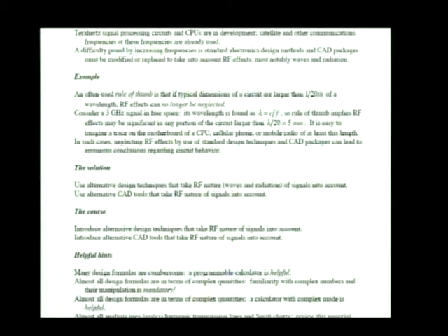That's a pretty tiny distance. Still, 5 millimeters. Pretty small. You know, the lead connecting one point in a circuit to a resistor is probably larger than 5 millimeters long. Definitely on a motherboard of one of these computers or in a cell phone or mobile radio or something, it's real easy to imagine that a typical dimension is bigger than 5 millimeters. So you have to make use of RF analysis techniques.